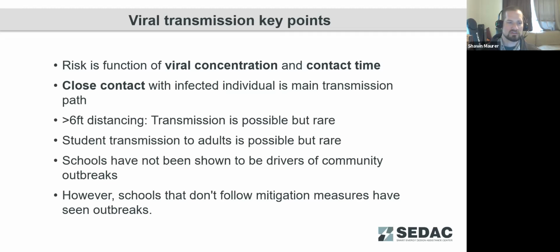So before we move on to the next section, we have another poll question to test your existing knowledge on mitigation measures for buildings and universal mitigation measures. So I did want to launch that poll now. Our first question, do you know what the minimum efficiency rating value for your filter should be to capture virus particles? MERV 7, MERV 8, MERV 11, or MERV 13?